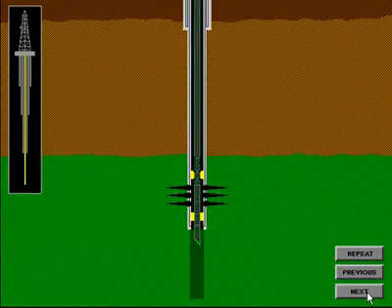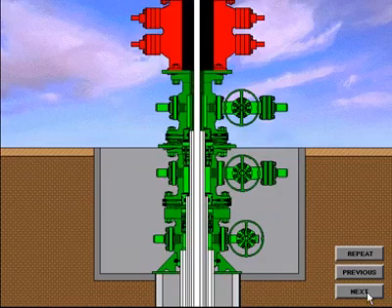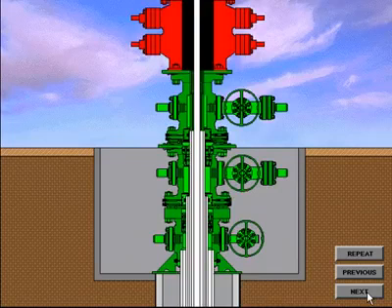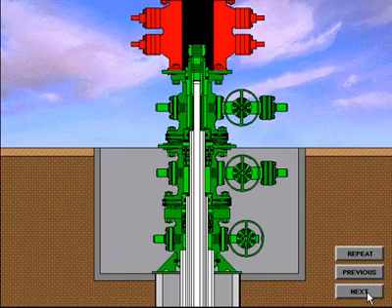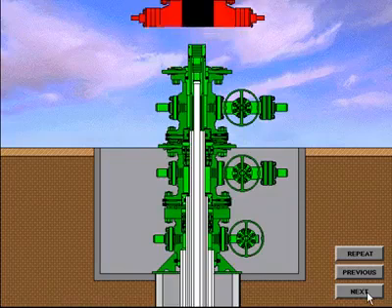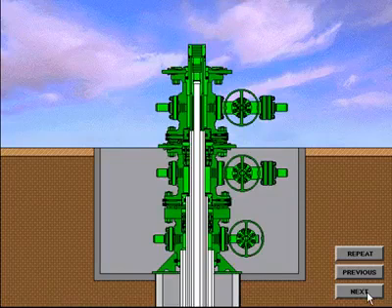The production tubing is run with a bottom hole assembly to seal inside the packer. After the tubing is spaced out and proper weight set on the packer, the tubing hanger is installed on the tubing at the rig floor, then lowered into the bowl of the tubing spool. The BOP system is nippled down and preparations are made to install the production Christmas tree.